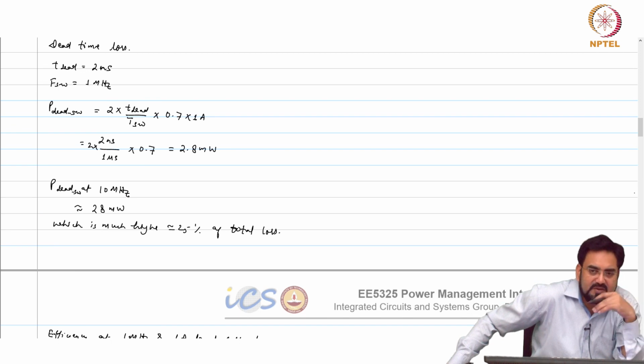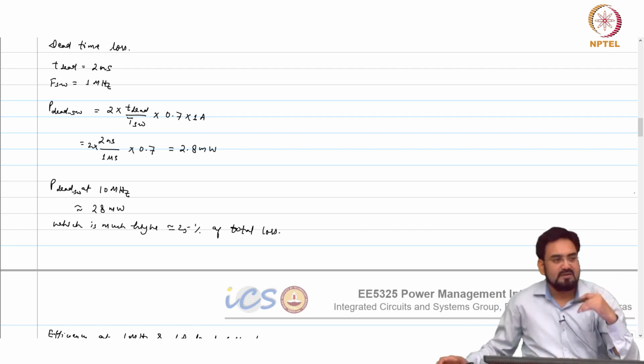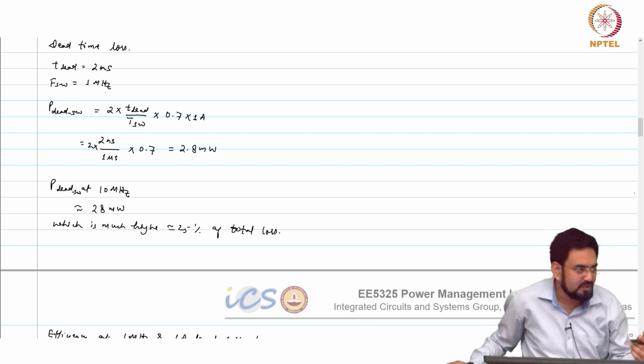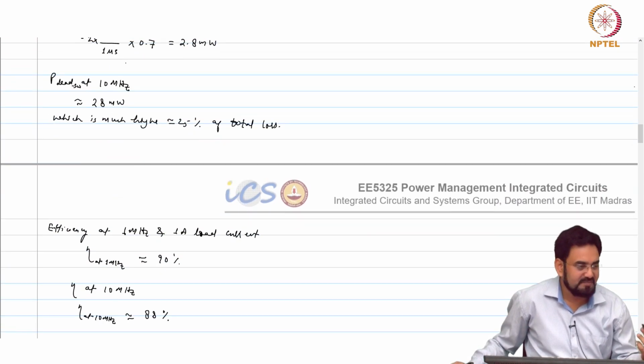So far, if you look at any product in the market, the targeted current is like 800 milliamp or so, or less than that. So 500 to 800 milliamp and 6 to 7 megahertz max frequency; going beyond 10 megahertz is very rare. But for this particular case, 0.18 micron and 1.8 volt input, 10 megahertz you can easily achieve.